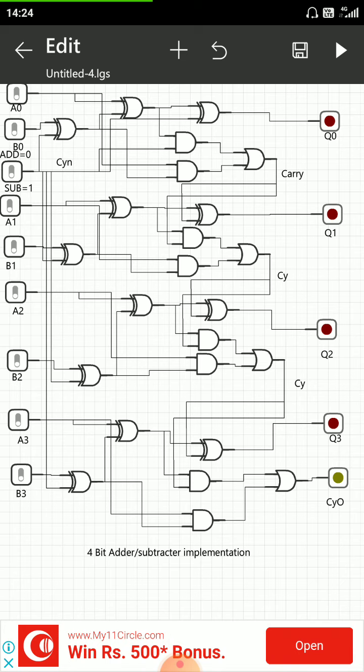Here we achieve this by adding an XOR gate, where a controlled inverting operation is performed when the logic is high. So carry input 1 is also added, so 1 is added to the 1's complement and our objective is met. Subtraction is performed in the circuit.